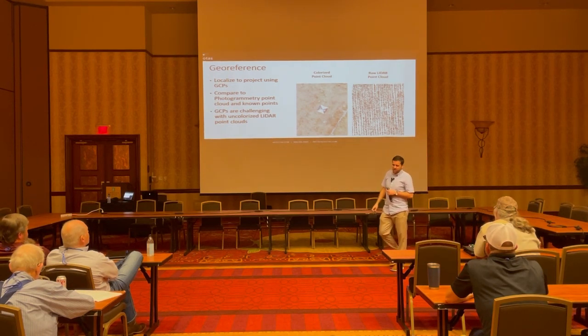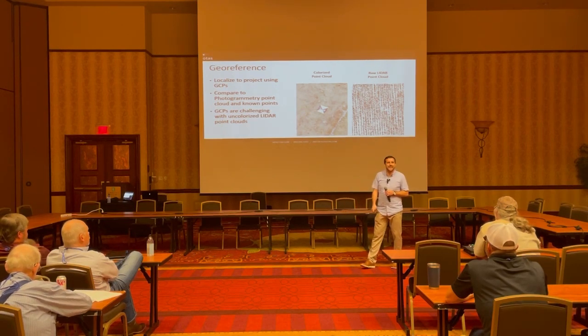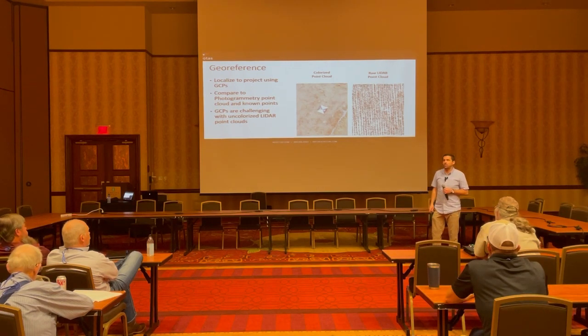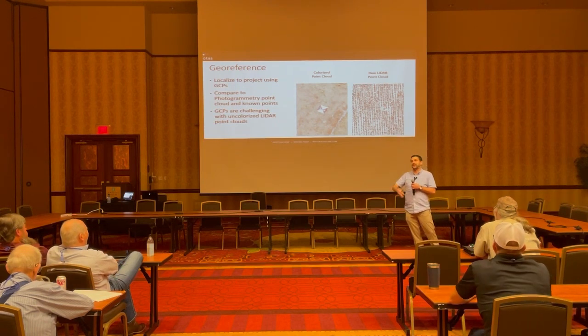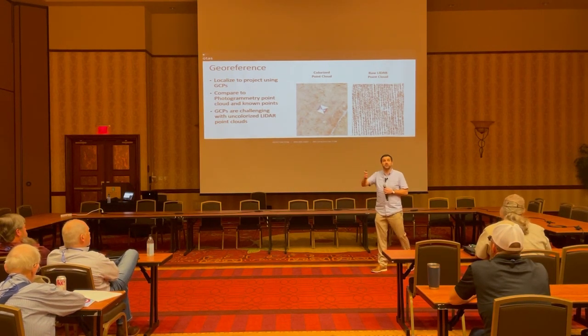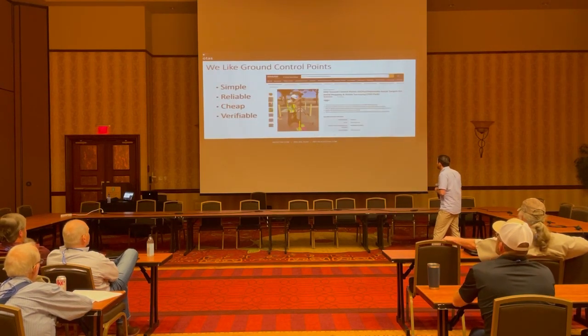There are other ways to do XY georeferencing on LiDAR data sets. You can use things like the intensity layer of a LiDAR point cloud to actually see X and Y, or you can compare it to known vertical points like the edge of a building or trees or things like that. But once again, it comes down to just having ground data to measure multiple points across the site to ensure that your accuracy is actually where you want it to be.